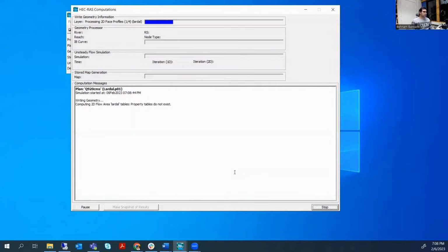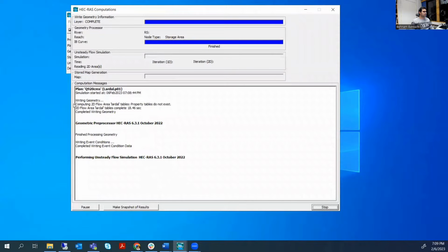Now I explain what the hydraulic warm-up is, which is very, very important in sediment modeling and also here. And I show you by a graph. Here you can see the model's information and the runs and the warm-up that we had here. If you remember, I added 10 now. From -10 till 0, we have a hydraulic warm-up that you can see here.